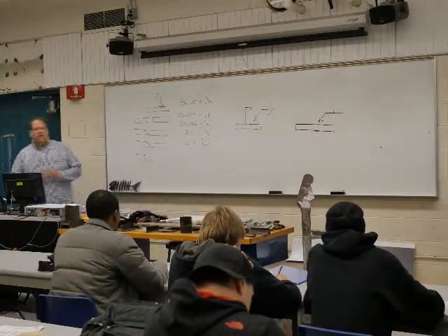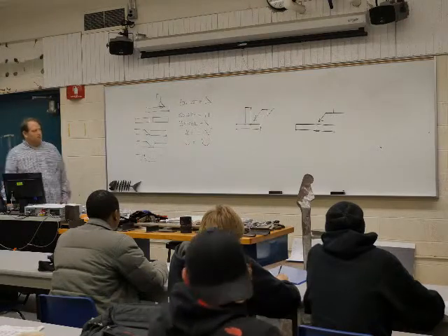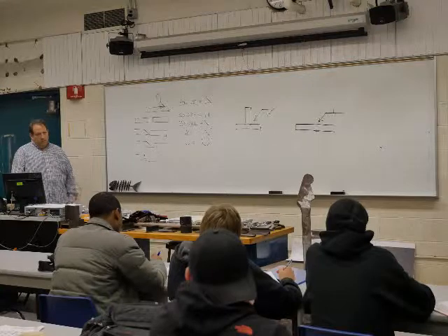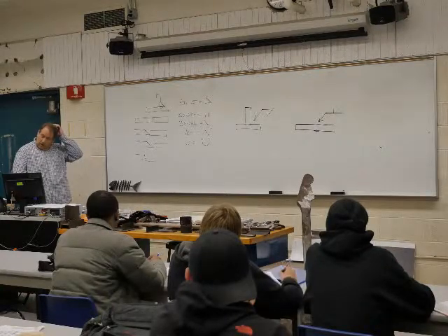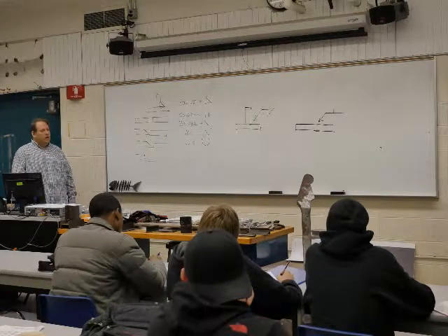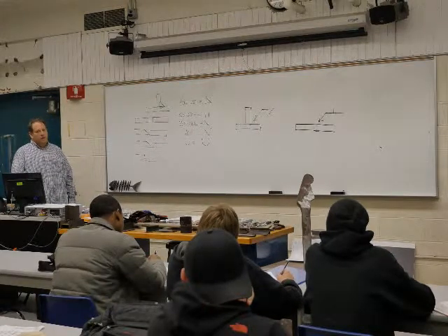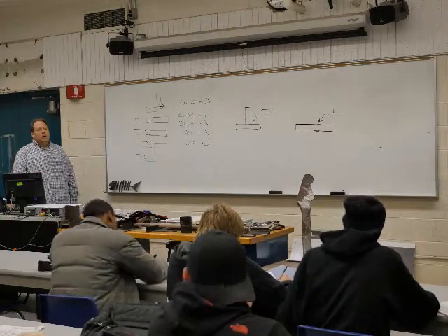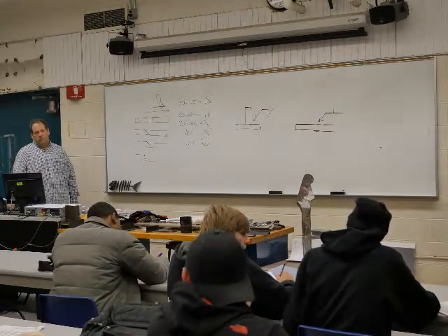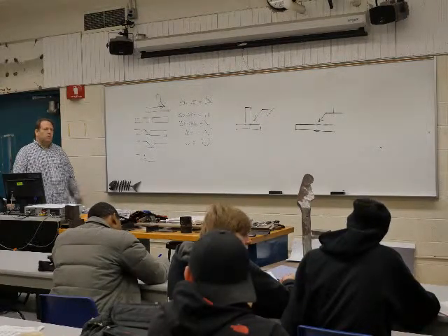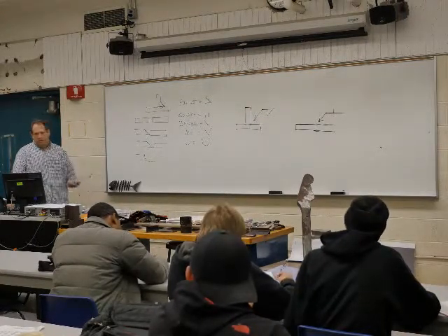Now what do we got? Fillet, same side. So, not same side, but V on the arrow side. Just making sure that when you're talking terminology for welding, we need to be kind of exacting because it could be taken different ways.